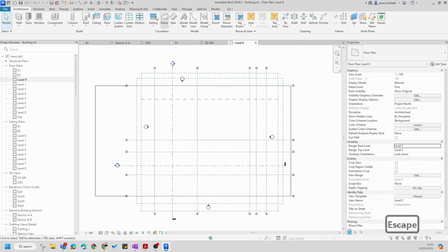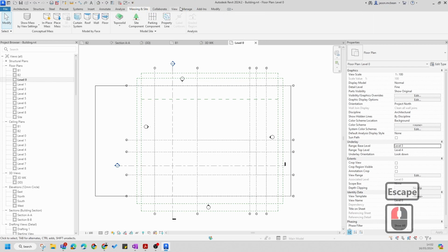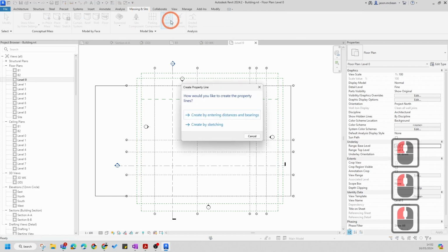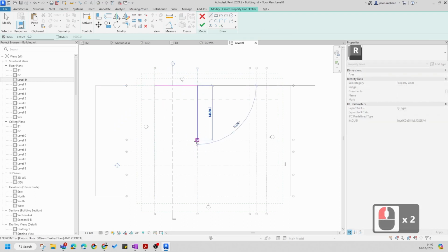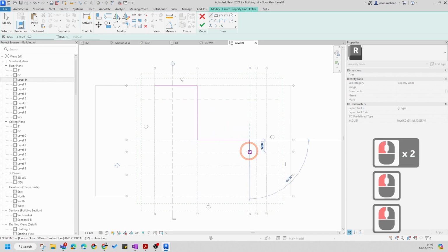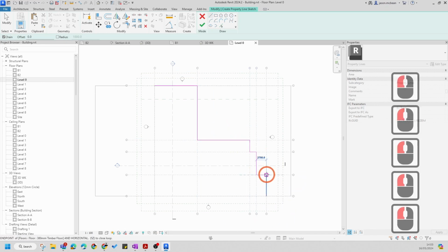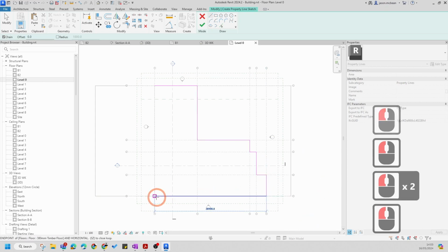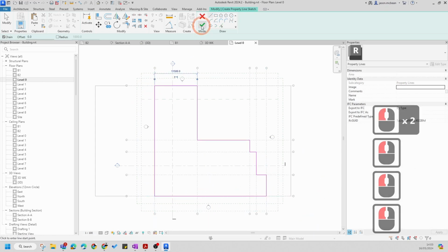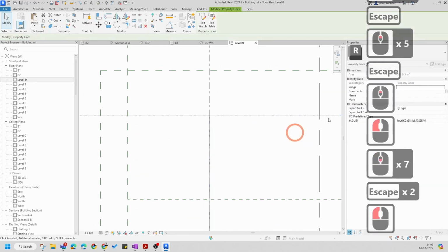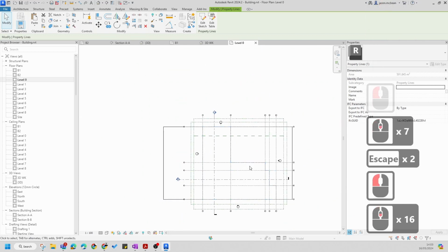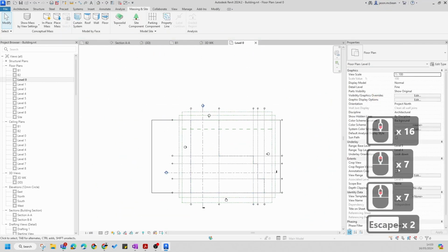Okay, so that's important. So what I'm going to do very quickly, this is totally up to you. You can do it or you don't have to do it. I just want to establish a property boundary in my building model so that I have a clear indication where my property boundary is. Ideally, you should have done this in your site model as well, but for now, I'm just going to replicate this in my building model because it will give me some constraints to work with on all my different levels. Press OK. Okay. Now, in essence, that makes a bit of line work, and it tells you it's a property line. It's a building line. Okay, so you can't cross that.